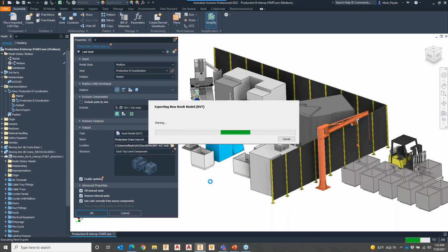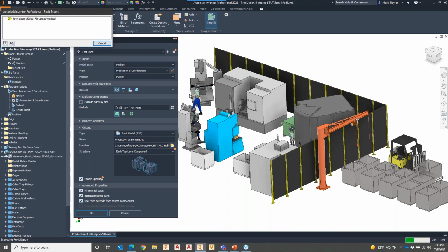Okay, now as this is exporting, I want to talk about a few other things with this. So when you think about BIM collaboration in the past, with RFA files, you had the option to put mechanical component connectors on there. So you can do duct connectors, you could do electrical connectors, you can do pipe connectors. Those you can still do, but they have to be done on an RFA. So for instance, if I were to look at this crane as the example, maybe this crane needs to actually have electrical connectors. Maybe this machine over here that's blue needs to have electrical connectors on it for Brian. I would probably exclude that from my RVT but I would have a footprint on the ground for where it needs to sit. That way, Brian knows where to put that piece of machinery.